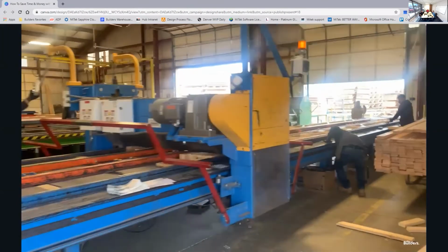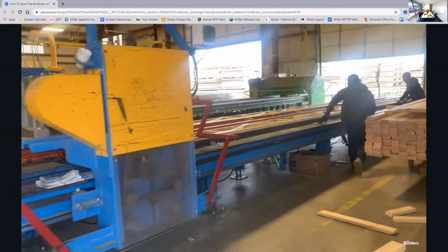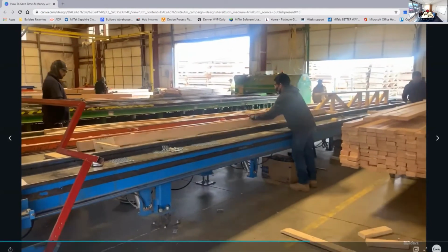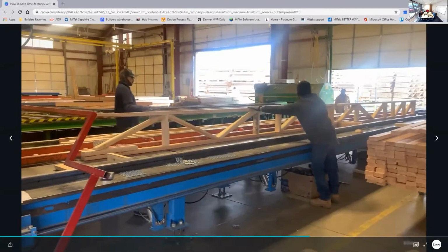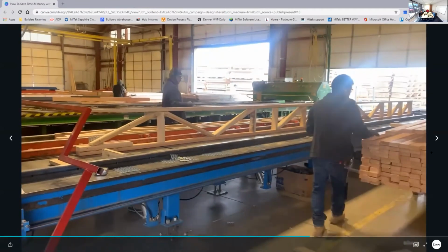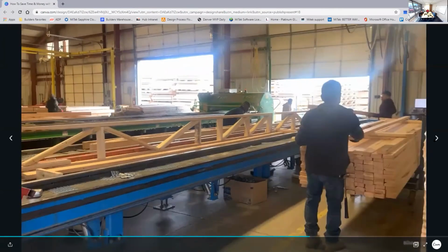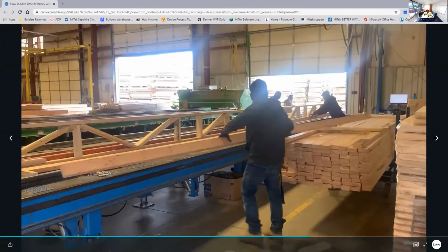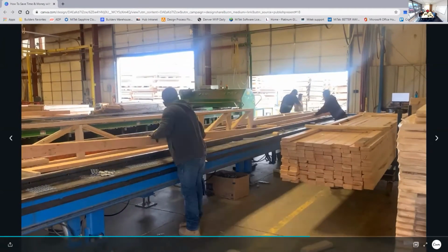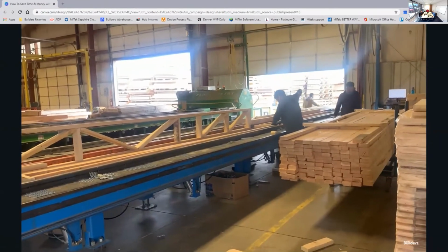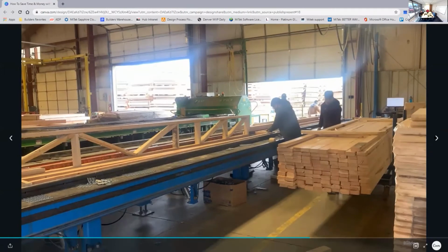So yeah, we can clear span great distances, up to 30 to 36 feet, depending upon the loads that it's designed for. The spanning ability is superior to a lot of other methods for putting in floors. So we'll watch the floor go out and then they flip the floors to the other section and they start the new floors, they put their webs in.